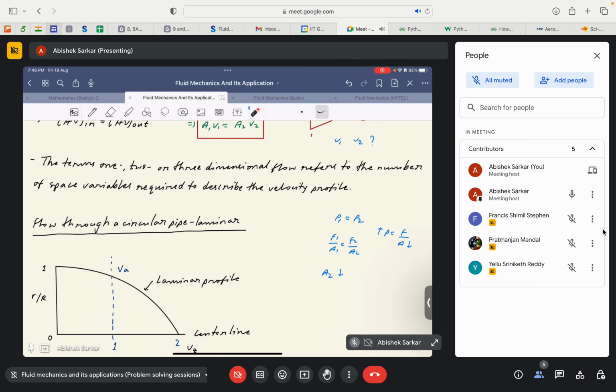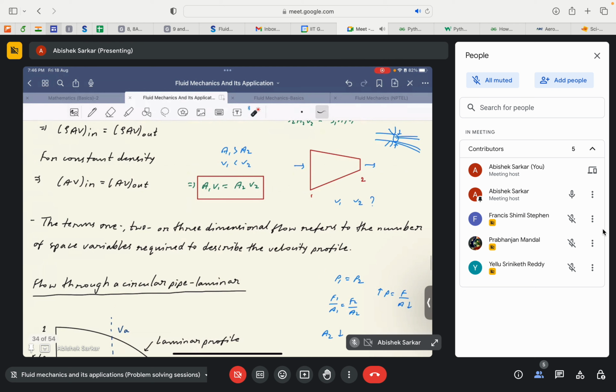The flow is now moving, it has some velocity, and the motion of the fluid itself will have a certain effect on the variation of pressure in the flow field. So we cannot directly imply that area reduction would imply an increase in pressure. In fact, we see that even if the area is reduced here, the pressure will also reduce in this case.